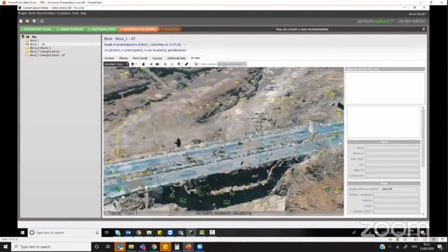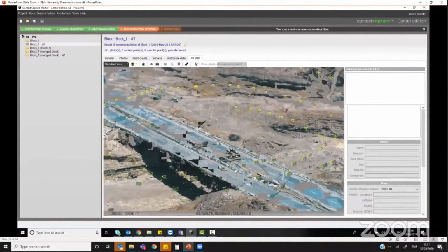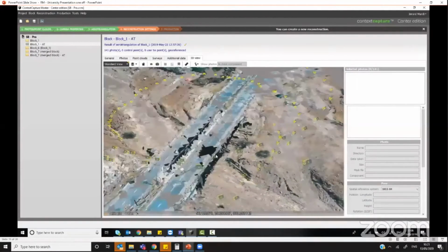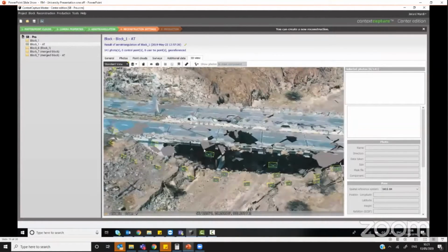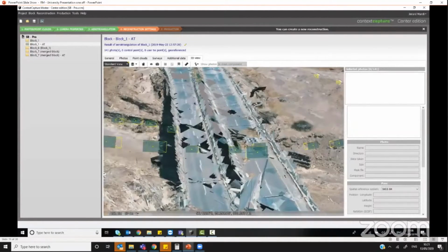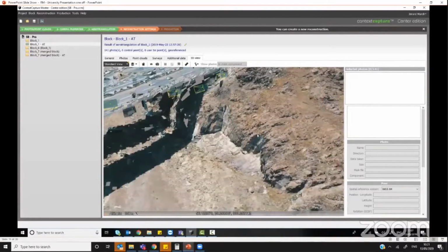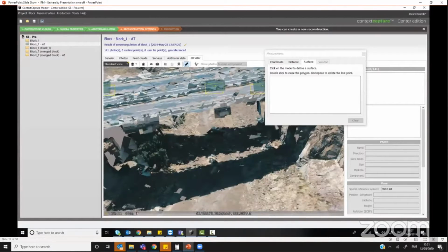What used to happen is when you'd run an aerial triangulation in any photogrammetry software, you just had lots of little what are called key points, which would make up your scene. And before you reconstructed, you'd struggle to work out, is everything looking correct? Is the detail correct? Have I got any bits that I've missed or any fill-in anywhere? This is where splats come in. What splats do is put a little thumbnail basically on your key points.